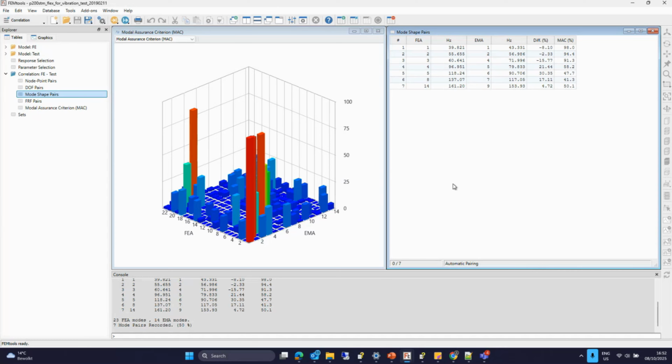That's why with lumped masses, you will typically see that the orthogonality check gives a different look at correlation, because no longer every degree of freedom has the same importance, but the ones where mass is concentrated get a higher weight. That can sometimes improve the capability to do mode shape correlation by favoring those locations where mass is concentrated.